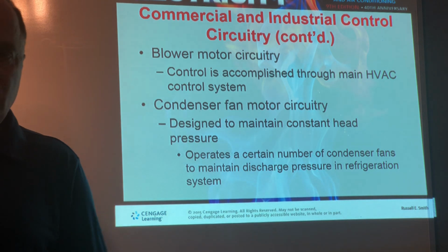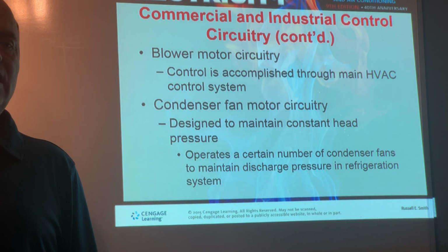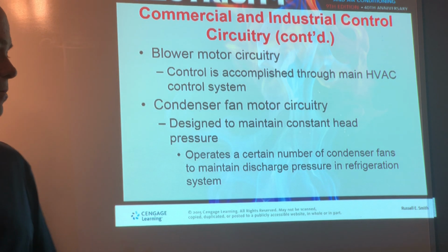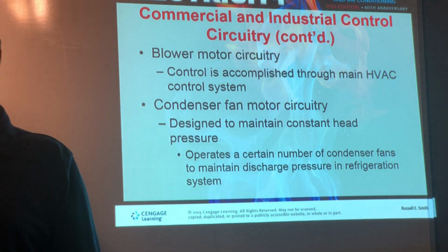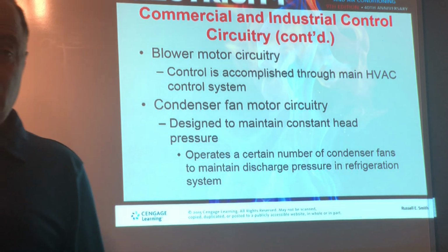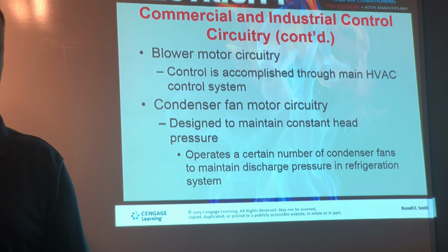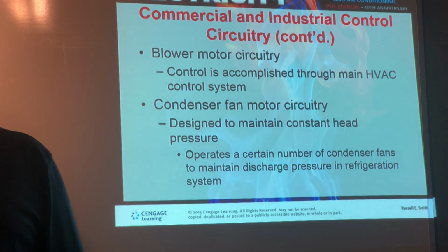Okay. Now, generally we talk about air handlers, an air handler being a separate component that is the air that we blow over maybe the hot and chilled water coils in a commercial industrial application. And this is the thing that really needs to operate the most, because especially in a commercial industrial building, whenever people are there and you're occupied, which quite often is more than you'd think in these facilities, especially with people working, doing repairs and cleaning the buildings, you need to have ventilation.